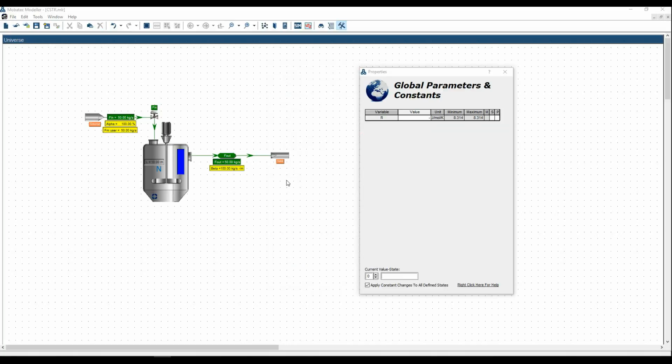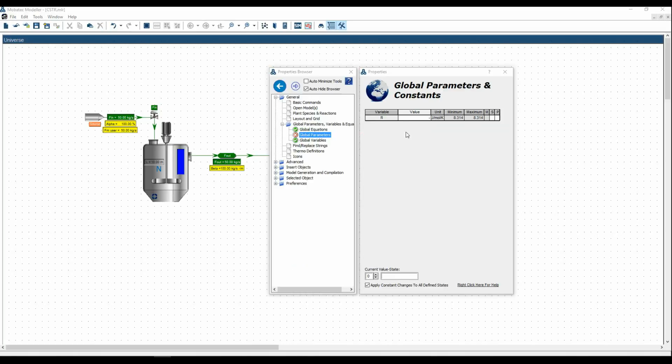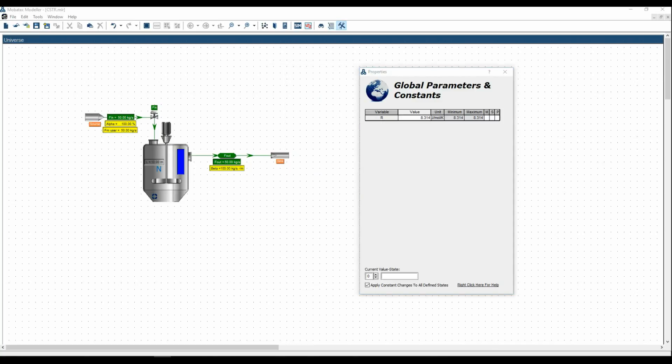Enter the gas constant parameter value, which is already limited by the minimum and maximum bound, which we defined once we declared the gas constant variable dimensions in the main editor tab. Enter 8.314. And now you can see that the global parameters are checkmarked green. Now let's initialize our CSTR capacity system.